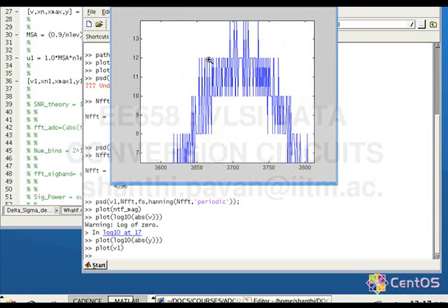you'll see most of the time that the output seems well behaved, and the jumps, you can see, for instance, that the output jumps by 2 LSB a lot more often than we saw in the second order case. I don't know if you remember, but with the first order case, we saw that the output was always jumping up and down by just 1 LSB, correct? When we went to the second order case, during the transition we found that occasionally some of those would jump up by 2 LSB. Okay. Here we see that this 2 LSB seems to be a regular feature, right? You can see that the jumps, especially around here, seem to be jumping up and down by 2 LSB almost all the time. Okay.